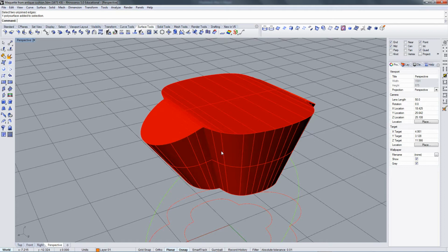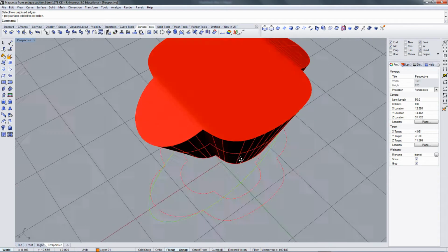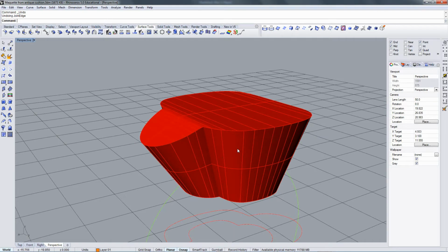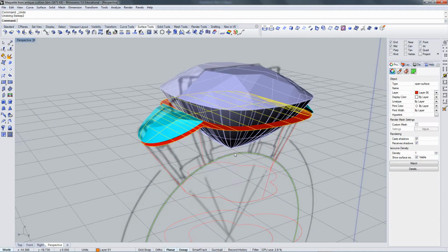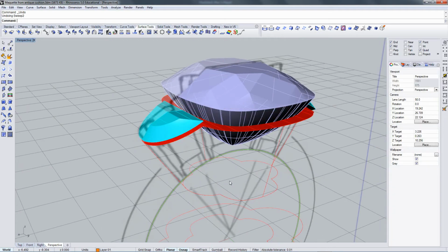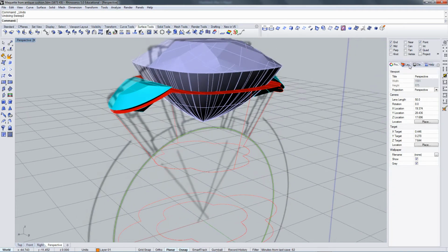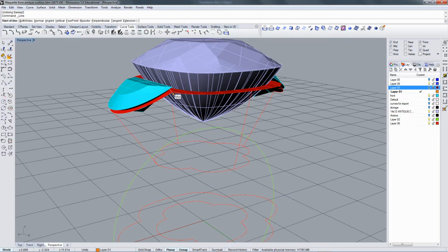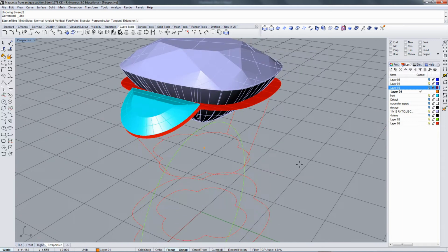So I can decide right now, class, with this just being a maquette, do I care that it's leaky or not? I kind of do. So going to undo the joint edge, and I'm going to undo the loft, or the bi-rail sweep. I told you I'm afraid there wasn't enough information there, and I was right. So end only. I want control here.